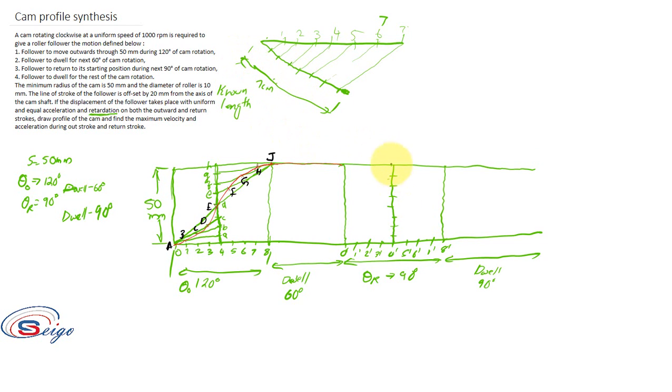a known length. So here, if you want to divide this line segment into 8 equal parts, you have to draw a line like this, which is having a 4 centimeter. Then you have to divide this 4 centimeter line of 0.5 centimeter each, join the endpoint of this line to this endpoint, then draw parallel lines. Then thereby you can divide this line segment to 8 equal parts. Okay, so this is your points A dash, B dash, C dash, D dash, E dash, F dash, G dash, and H dash.